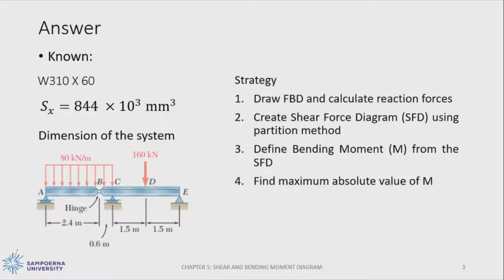The strategy used to solve this kind of problem is drawing the FBD and calculate the reaction forces. And then the second, we need to create the shear force diagram or SFD using a partition method. And the third one is by defining the bending moment from the SFD. Then last one, we need to find the maximum absolute value of M.